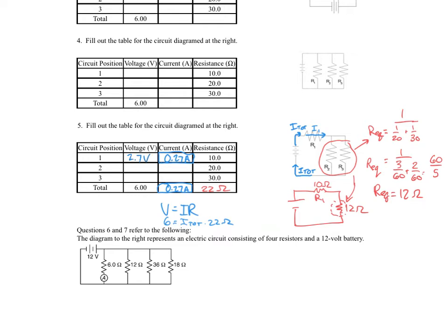And if you notice down at the bottom, I have to drop 6 volts total. So my battery pack has 6 volts from the high side to the low side. And if I drop 2.7 just by going across that first bulb, I started at 6. Think of it like a hill analogy. I'm going to draw up here. You're starting at a height of 6, and then you just dropped in height a total of 2.7, as your delta, your change in height.